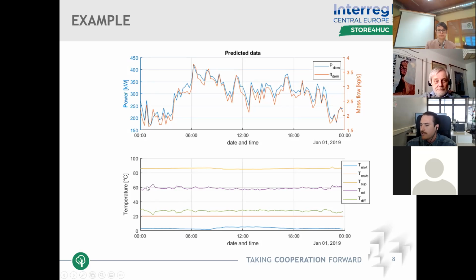So I would conclude that the system works in a way that it has a fixed supply temperature and return temperature, and it changes the flow of the pumps accordingly to keep it that way.